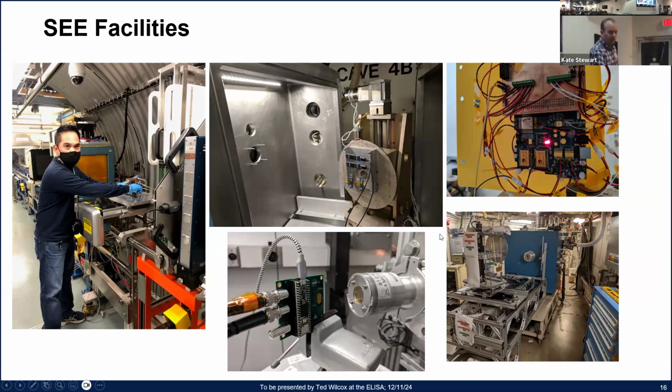Okay. And then really the newest entrants to this field are some of the medical proton therapy facilities. So in the upper right, this is a Virago single board computer being tested at the Massachusetts General Hospital. So we piggyback on the 200 MeV proton beams that are performing cancer treatments during the week and are often performing electronics parts testing over the weekends or on dedicated rooms, sort of segregated from the medical facility. So there's a number of these facilities that have cropped up over the last decade and a half, performing this type of work, especially for the commercial space industry.